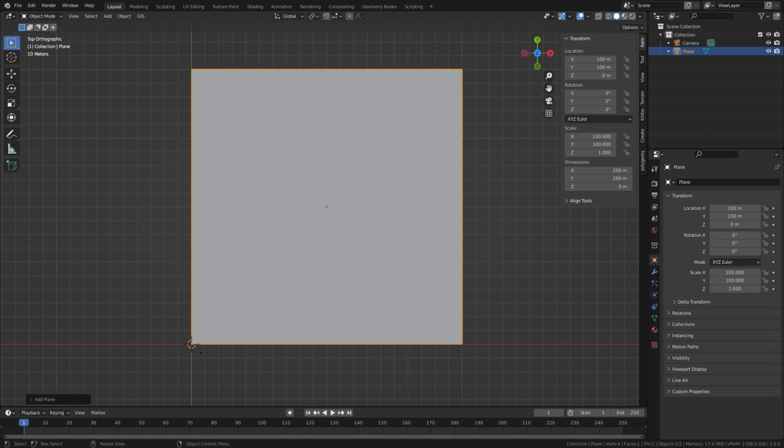Now, just another reminder, you could have had a height map already created from Leveler, L3DT, a mesh from somewhere else, or a point cloud that you did. As long as it's a plane and you have it imported into here, I'm going to show you how to create the material that we need to actually get it rendering out as a correct height map file, as a PNG that you can then convert into RAW or use as a PNG in the Resolute track builder helper.